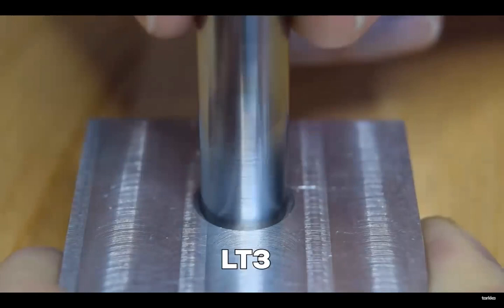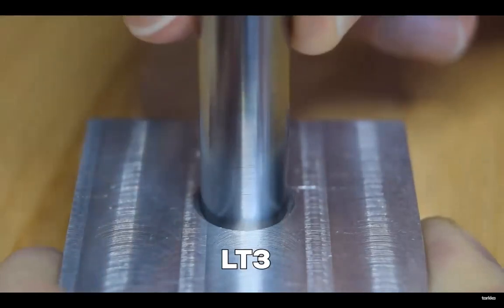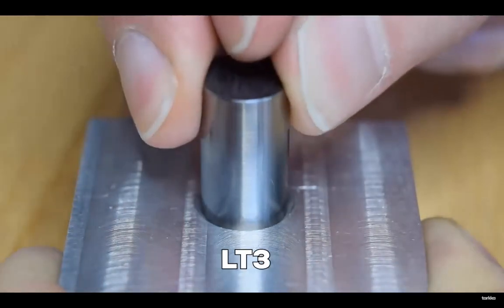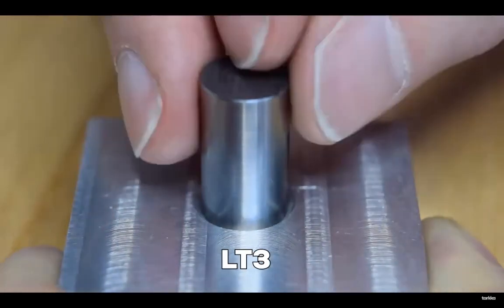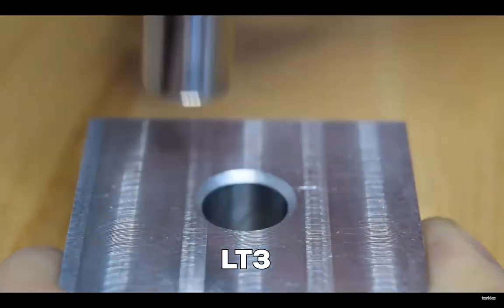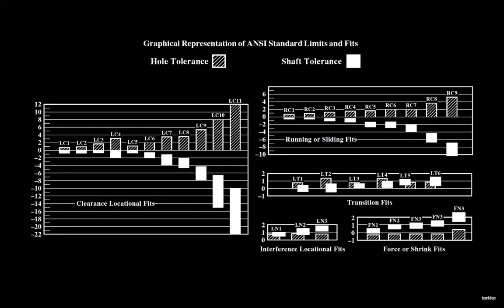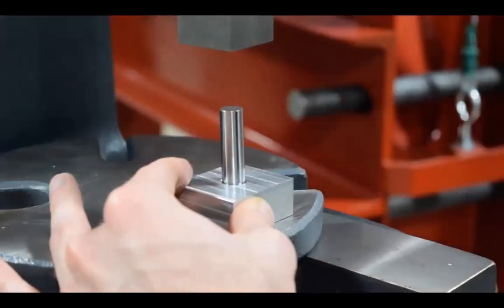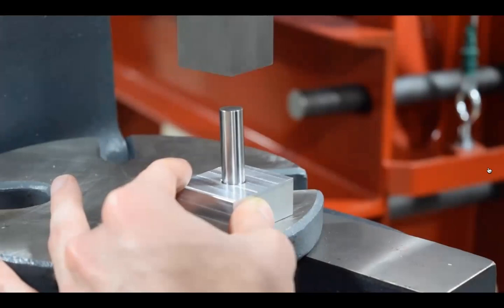This next type of fit is called a transition fit, and it requires a slight amount of force to assemble and disassemble. However, there's absolutely no play once the pieces are assembled. The tolerance required for the LT3 fit is about the same as the RC3, but the range of the shaft has been shifted so that there's a slight amount of interference. If we add a bit more interference, we create what's called a force fit or a press fit. These fits usually require a press to assemble and are intended to be a permanent connection.